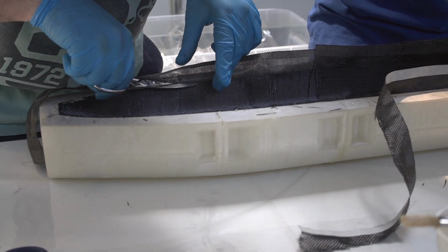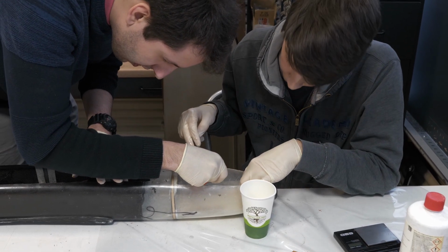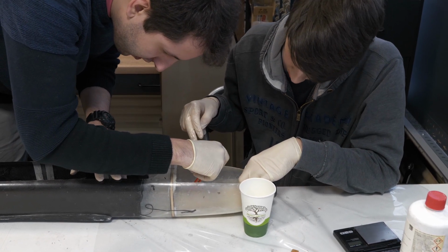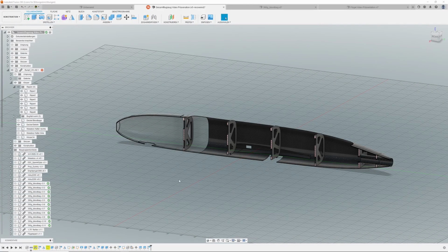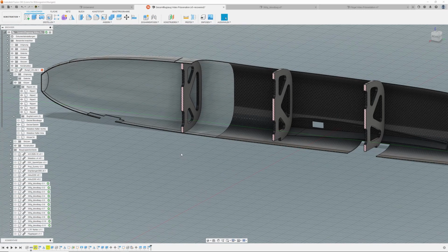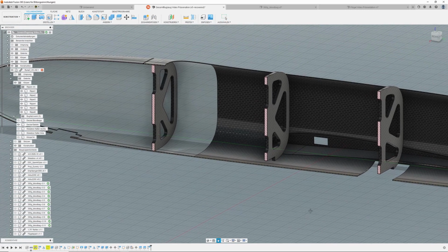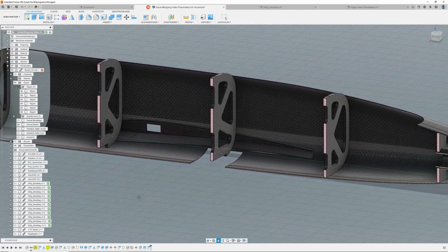The fuselage consists mostly out of carbon fiber. Only at the front we used glass fiber, since carbon fiber blocks radio communications. The outer skin is reinforced with composite ribs. They also act as dividers for the cargo bay, securing the payload during flight.